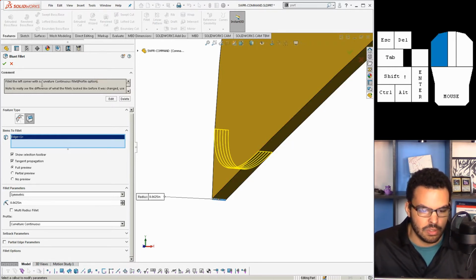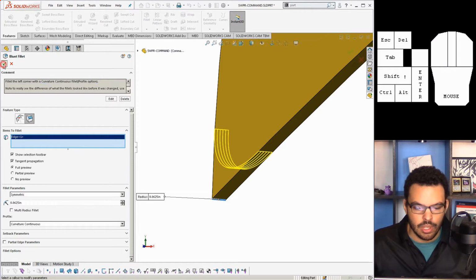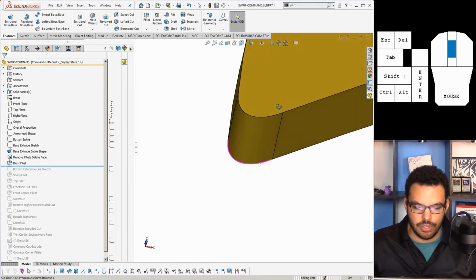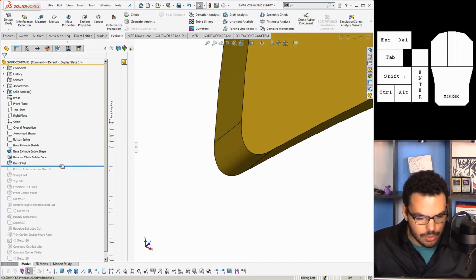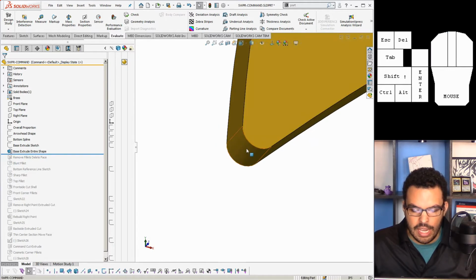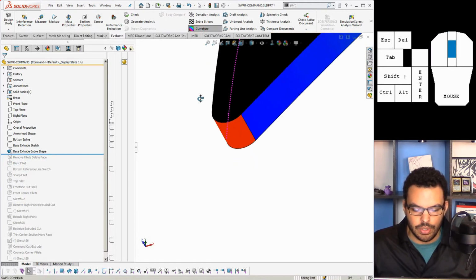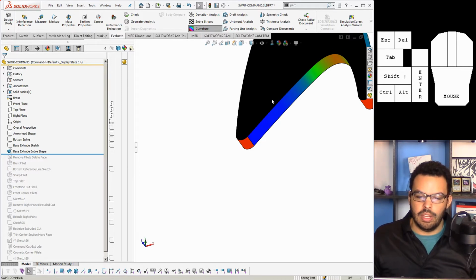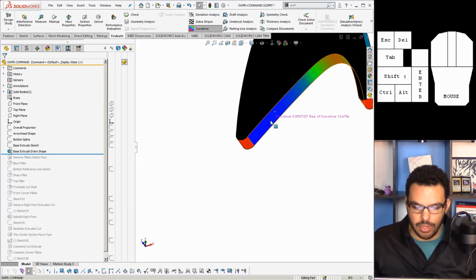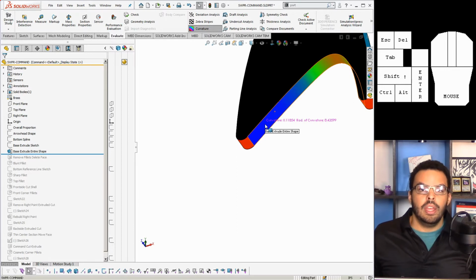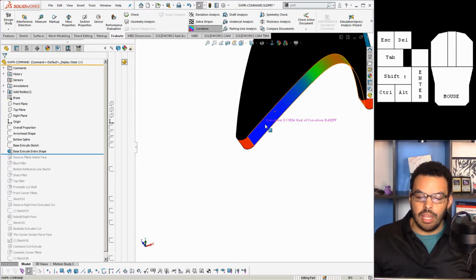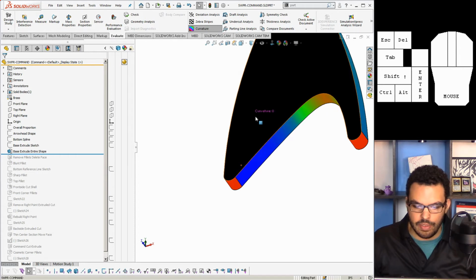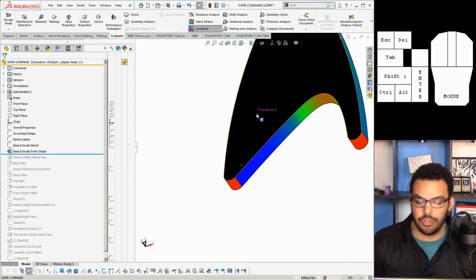And yeah, look, he mentions it up at the top here. So let me show you exactly what the difference is with curvature display. If I go to my evaluate, so actually let me go back here. So that's the analytical fillet. So if I go to curvature, remember what I said about this in my other video, the hat video pretty much. When curvature display is on, any particular radius will get a certain color. If the face is completely flat, it'll get black as a color. So that explains this. If I hover my mouse over, it says curvature 0, as it should.